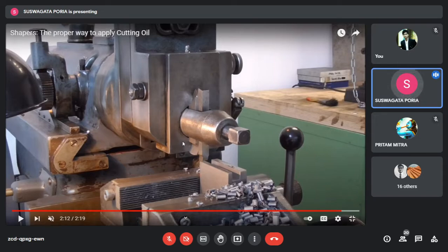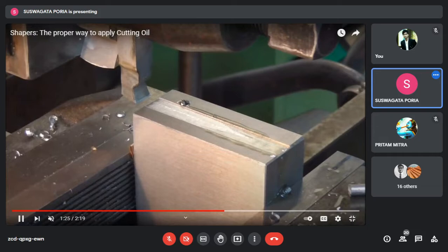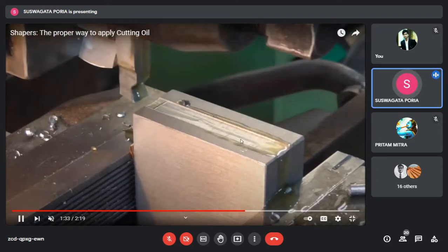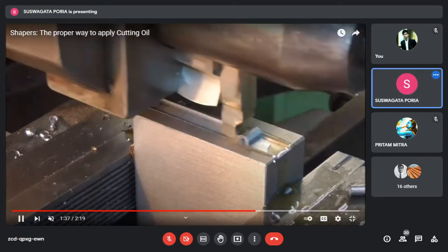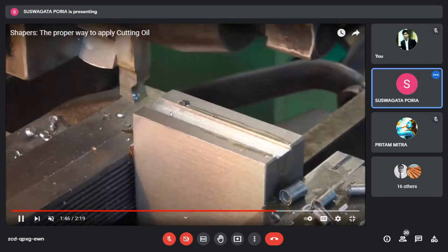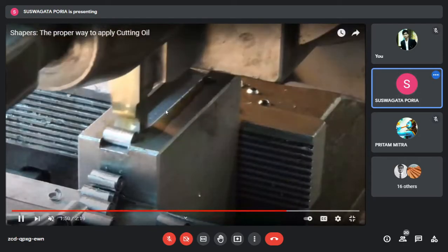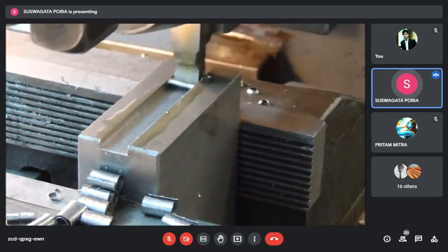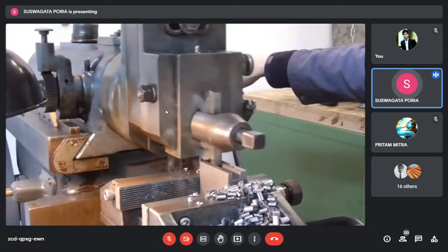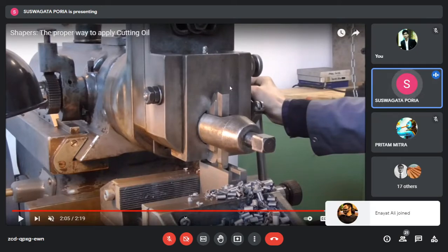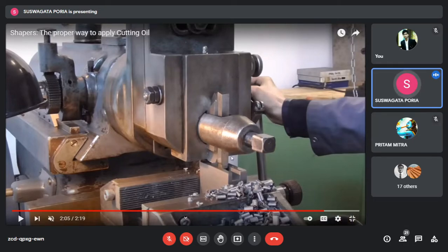The third purpose is that here the cutting is not much big. By one pass, two passes, three passes, four passes, the depth is increasing. The depth of the slot is increasing, meaning more and more depth of cut is given to the cutting tool. Depth of cut means the cutting tool is going in the vertically downward direction with time. After a single pass, it has gone a little bit downward so that more and more depth can be achieved. So there is a direction of tool movement in this. Follow my cursor. In this direction, vertically upward, vertically downward, a direction is there.